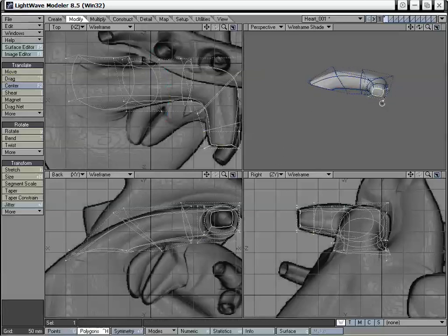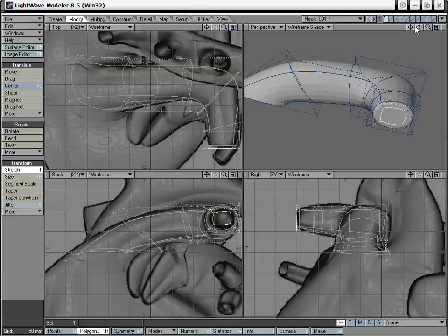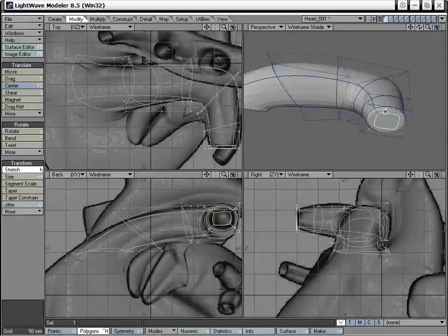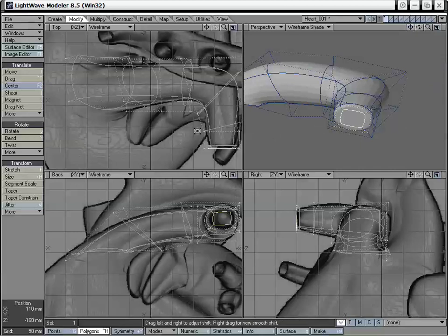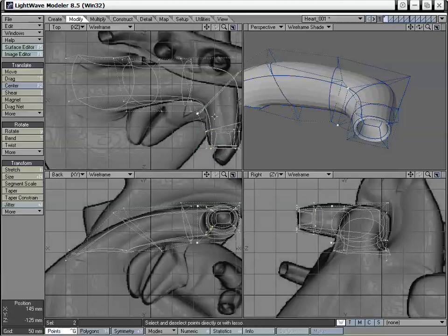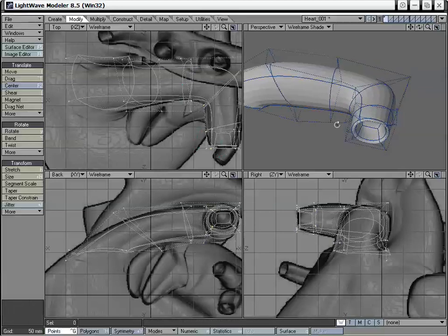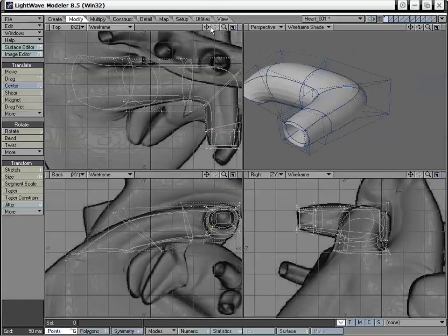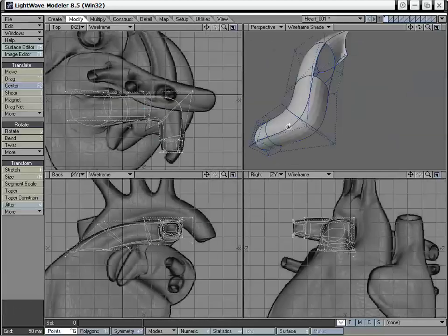We'll grab that polygon, Shift F, right mouse click, H, because we're actually doing the start of that hollowed out area. So we do not need to move it right away. And then Shift F again, smooth shift it, right mouse click, T to move. We'll just move it a little bit inward, H, stretch it so it's nice and kind of rounded. But we are going to be working on that later and actually making that so it is nice and hollowed out in the inside.